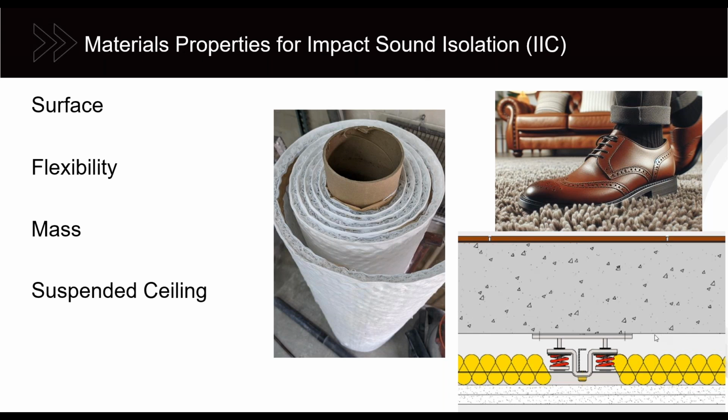If you can't isolate at the surface, there's an option to isolate at the ceiling below. And there are some circumstances where you are kind of forced to do that. So they have an isolation spring system that will isolate that gypsum board from the building structure. Mass is also critical, and the presence of a suspended ceiling in general is also very important.